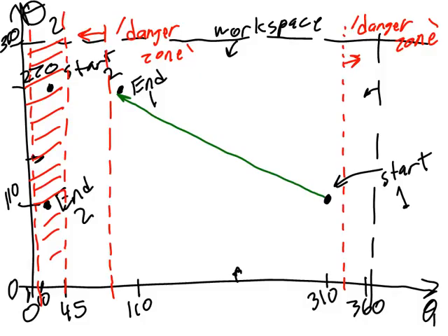In configuration space, those collisions will look something like this. At the far end of the collision, when the danger zone just begins, there's only one value for theta 2 at which this collision will take place. For example, I think in our example, it would look like this.